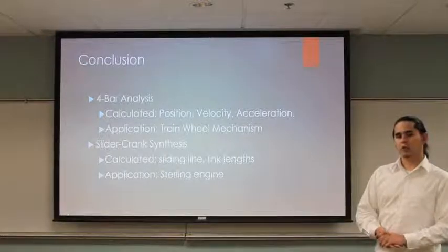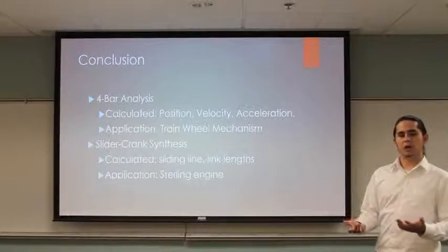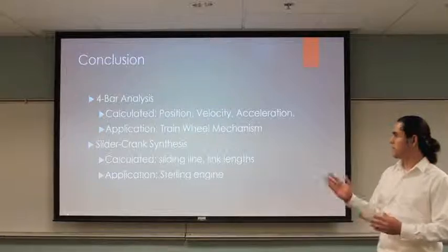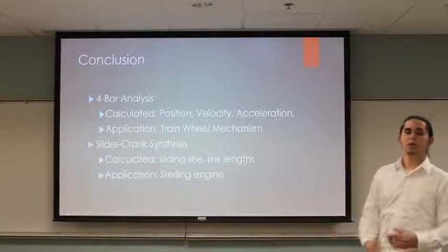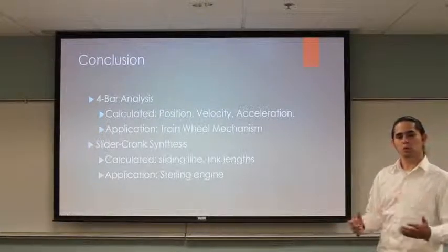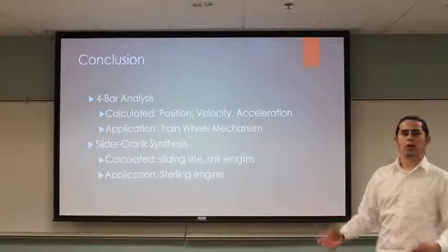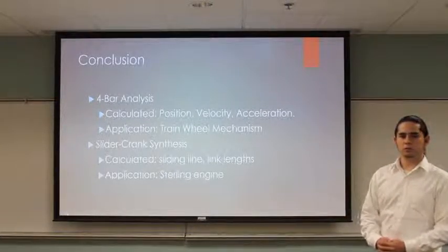For a slider crank, after evaluating the possible geometries and finding the sliding line and the possible link lengths, we determined that the mechanism was most suited as the crank and connecting rod of a Stirling engine.